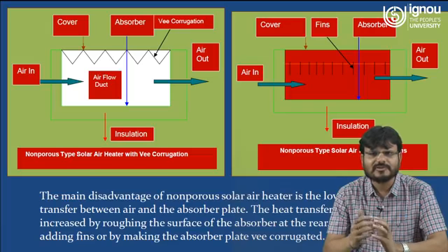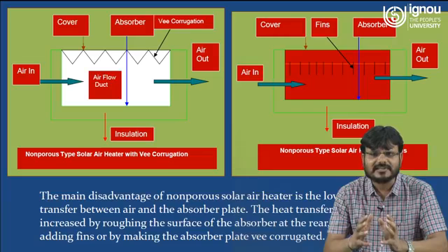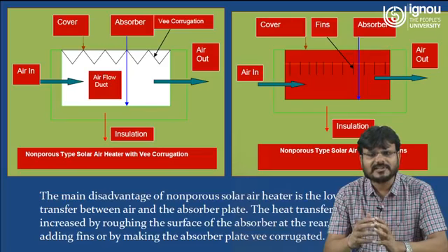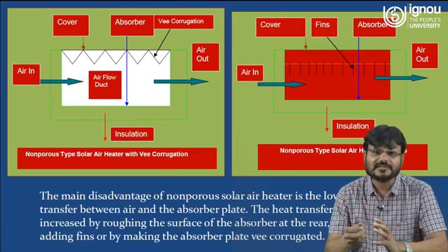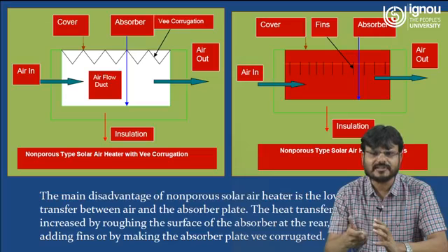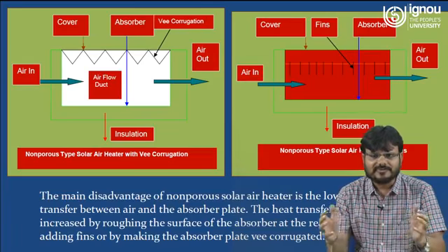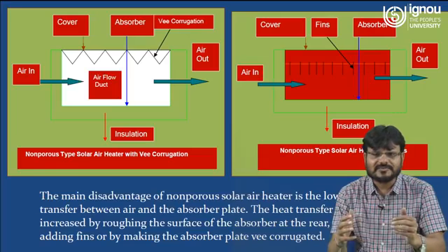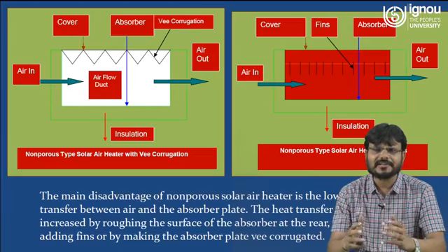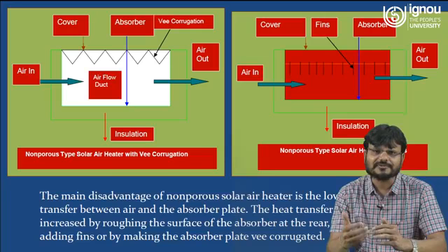So if you are using a number of fins in the air chamber, that means you are able to increase the collector area. If you are able to increase the collector area, that means heat associated at the collector is more, that means you are getting more thermal energy, and this associated thermal energy will transfer to the working fluid, that is air, and this hot air is coming at the outlet point. So you are getting more heated air. That means the difference in temperature is more. If the difference in temperature between air in and air out is more, that means you are getting more thermal energy.